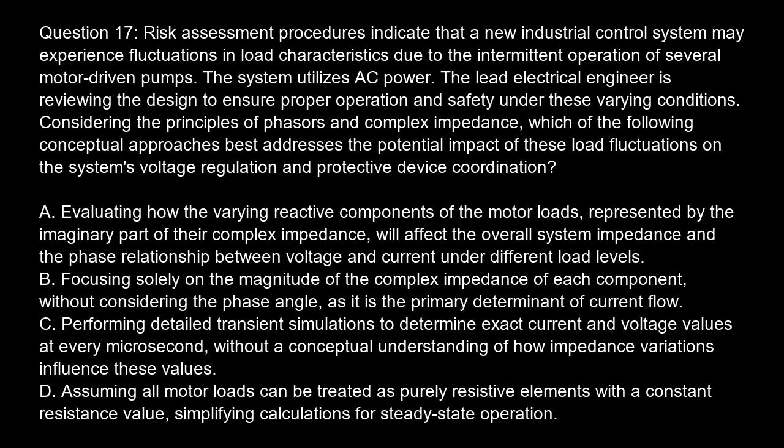Option A. Evaluating how the varying reactive components of the motor loads, represented by the imaginary part of their complex impedance, will affect the overall system impedance and the phase relationship between voltage and current under different load levels. Option B. Focusing solely on the magnitude of the complex impedance of each component, without considering the phase angle, as it is the primary determinant of current flow.